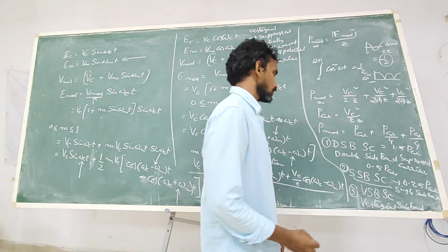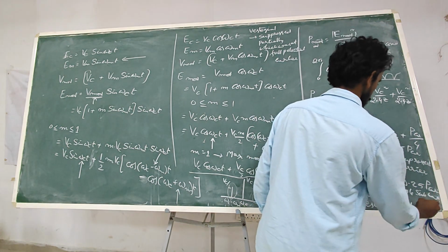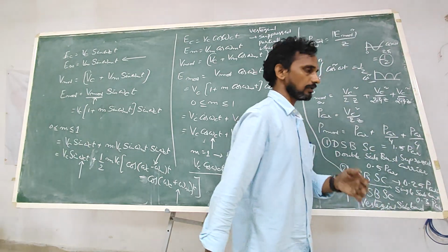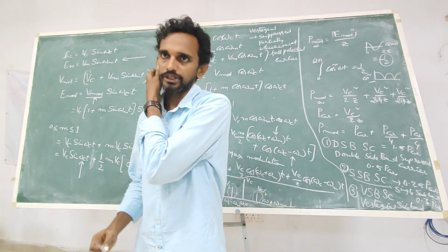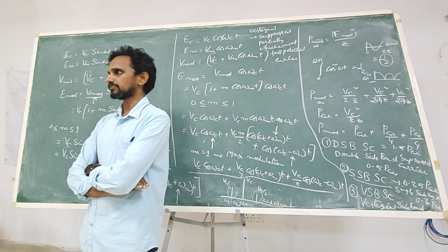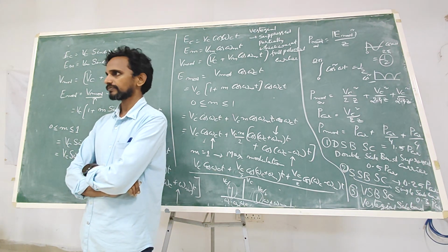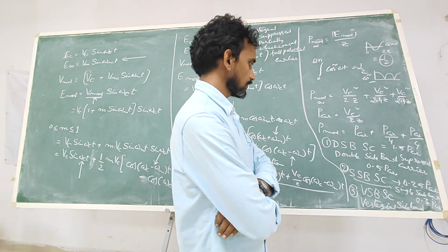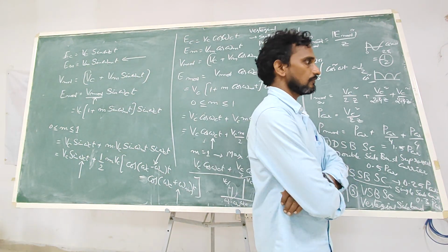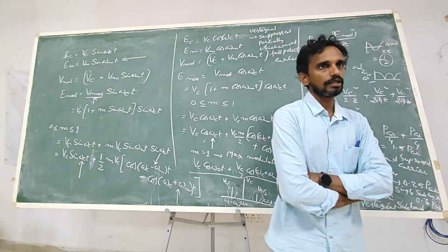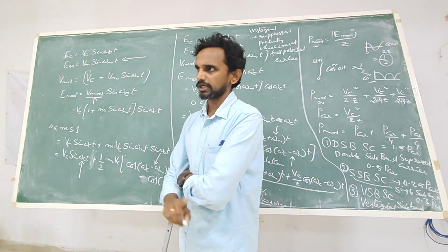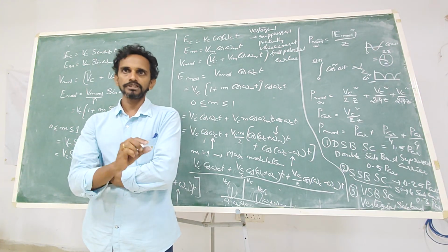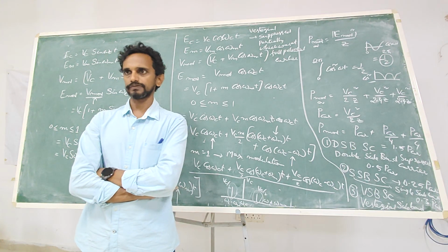So this will have power requirements between 0.25 and 0.5 times, more than 0.25 and less than 0.5. This is widely used for analog TV communication, where one sideband is used for the video signal and the partial sideband is used for the audio signal.